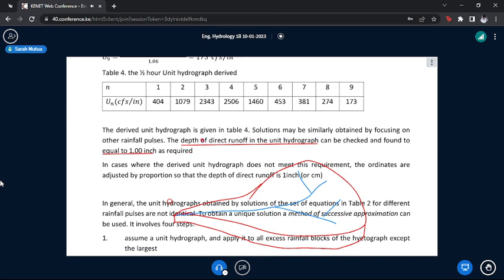We have to convert all the input data into consistent units, because rainfall is in millimeters and discharge is in meters cubed per second. This is how you convert a discharge into a depth: you assume the discharge is flowing over an area, and you distribute that volume over that area.